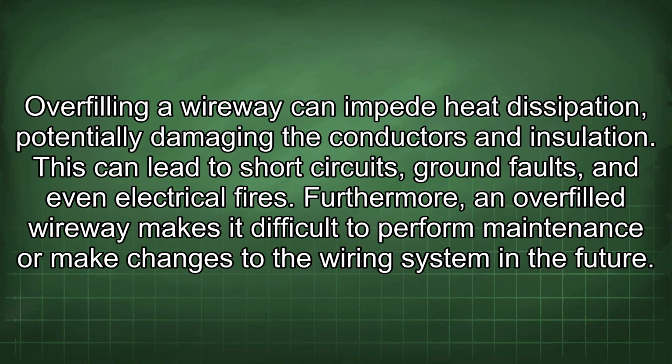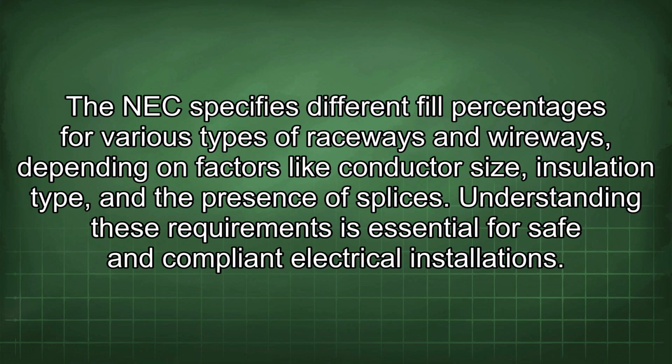Overfilling the wireway can impede heat dissipation, potentially damaging the conductors and insulation. This can lead to short circuits, ground faults, and even electrical fires. Furthermore, an overfilled wireway makes it difficult to perform maintenance or make changes to the wiring system in the future. The NEC specifies different fill percentages for various types of raceways and wireways, depending on factors like conductor size, insulation type, and the presence of splices. Understanding these requirements is essential for safe and compliant electrical installations.